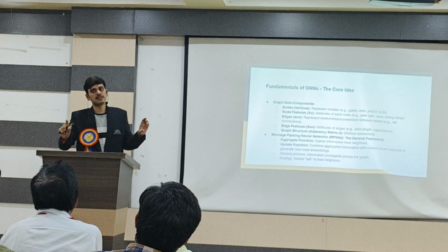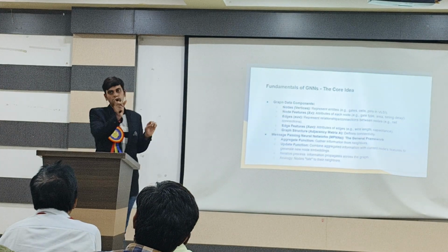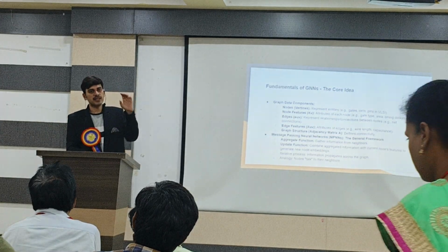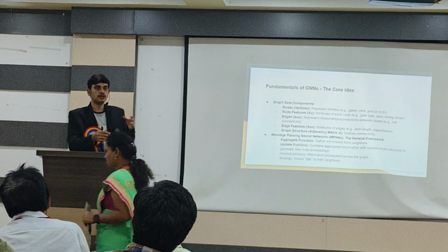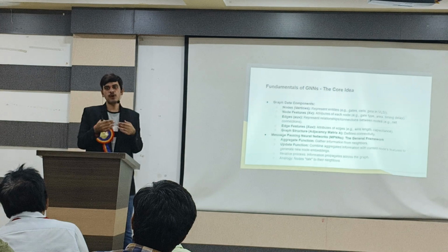So same cells. Where the difference comes is the net length and net property. That extrinsic delay, which is the net delay, the capacitance of the net is more in the other case. If it is more, the delay of the net is more. So based on that, we have to decide whether to use a higher drive strength or to break the net. These are the fixes we do on the net.